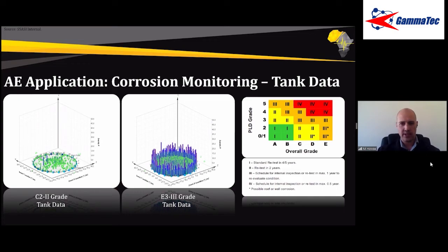And the way the location mapping works is more zonal than anything else. Because of complex structures, you don't know exactly where the sound path will go, so you can't get your timing difference correct because you don't know the exact distance. So you attach many sensors and do zonal location on it.